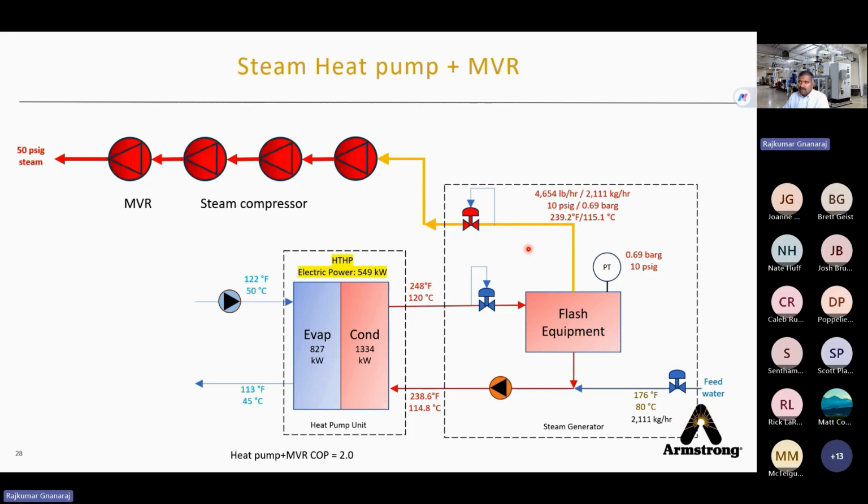In that case, imagine if the heat pump is switched off and all the steam in this line gets condensed to liquid, and then the vacuum gets generated in the flash vessel. It pulls the air inside it. Now you have got cold condensate inside the flash vessel that will react with the non-condensable gases. It becomes carbonic acid and it starts eating the equipment.